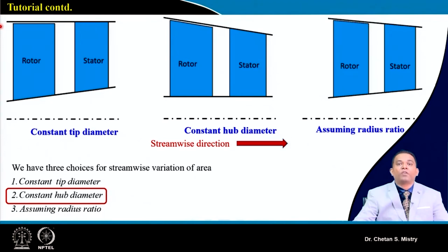If we consider our pressure ratio to be higher, that gives a higher density, and in order to maintain our axial velocity constant, our exit area decreases. If we configure a constant tip diameter, then my hub diameter will change between my entry condition and my exit condition.